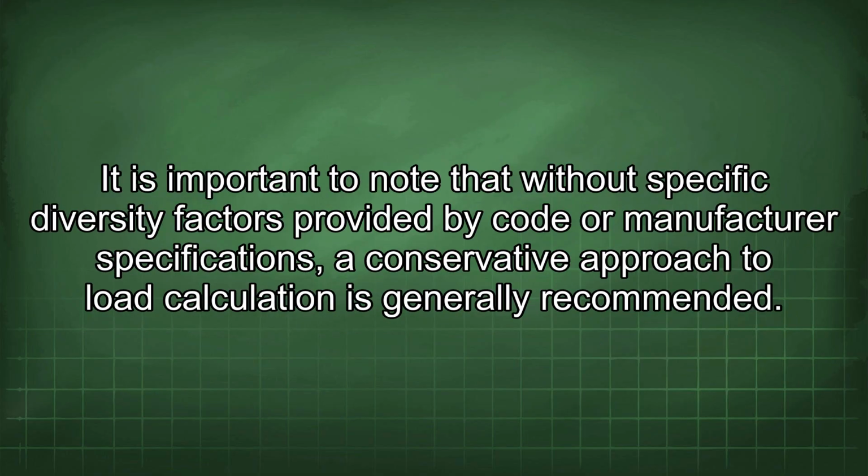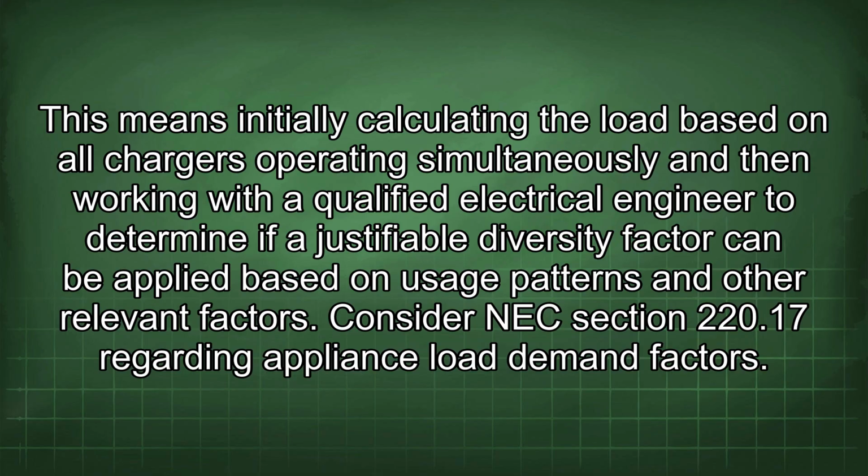It is important to note that without specific diversity factors provided by code or manufacturer specifications, the conservative approach to load calculation is generally recommended. This means initially calculating the load based on all chargers operating simultaneously and then working with a qualified electrical engineer to determine if a justifiable diversity factor can be applied based on usage patterns and other relevant factors.